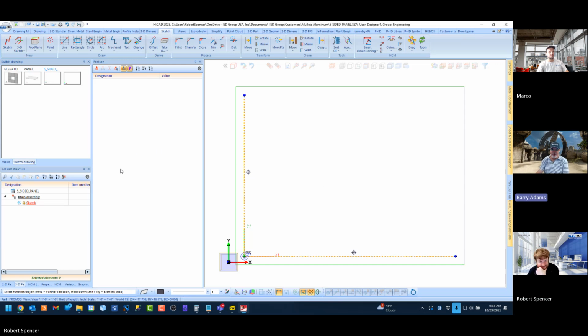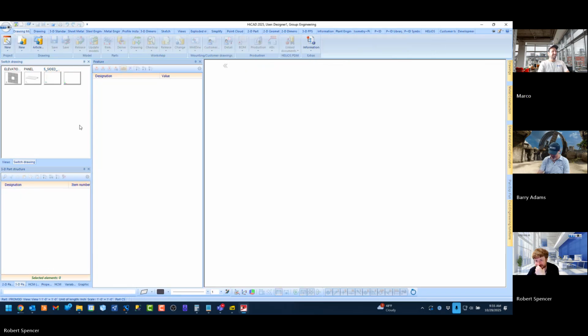Remember, I could hide my own Easter eggs. So if you know a drawing saved in the autosave process, you know how it pops up down here every so often. I think it's 20 minutes or 15 minutes. You can change that interval, by the way.